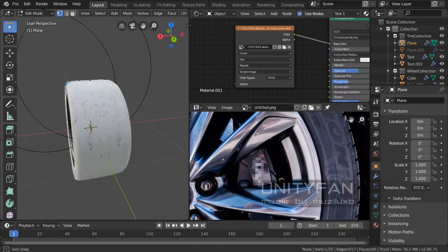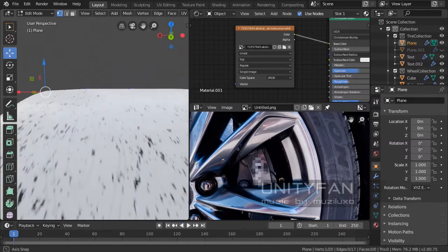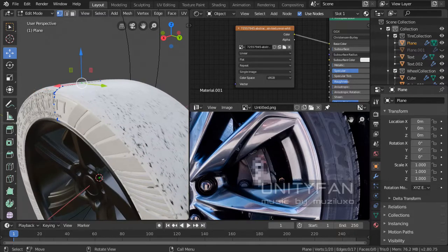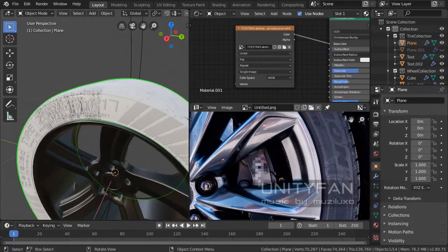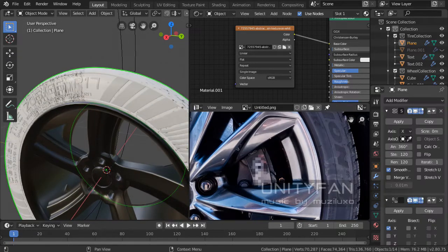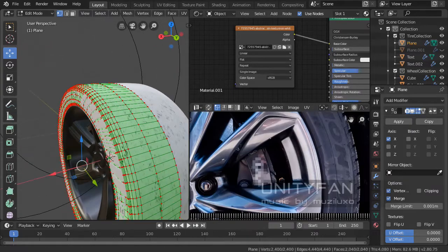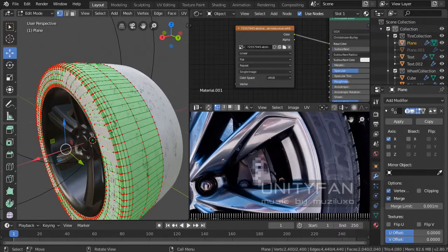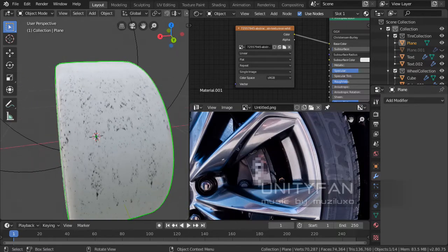Right now, for modeling reasons, it's just one line with the screw modifier on it. In order to change it, we have to apply that screw modifier to get the geometry to look like this. Also probably the mirror has to be applied too.